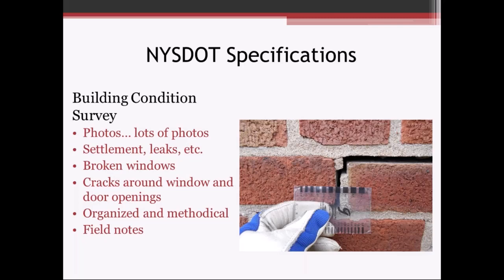A good building condition survey, people that do it, they're very methodical, they're very organized, they take really good field notes, and the pictures are well organized also. But I can't overstress the importance of taking lots and lots of pictures. I mean, these days, 20 years ago when we were doing condition surveys, digital cameras weren't nearly as popular.